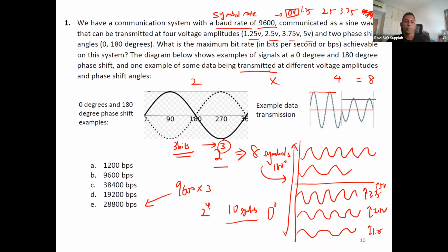So you basically need to make sure that the number of bits you select is enough to support all the symbols you need to support. Correct? So if I have 10 symbols, 3 bits is not enough, 4 bits is more than enough, but that is the smallest number that supports them. So you have to go with 4 bits.